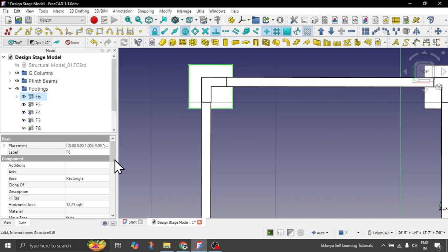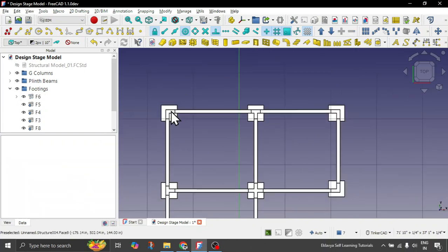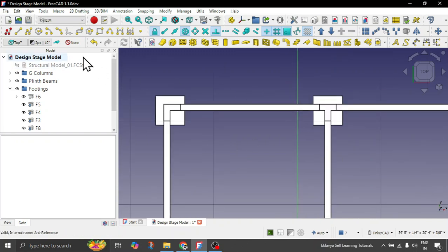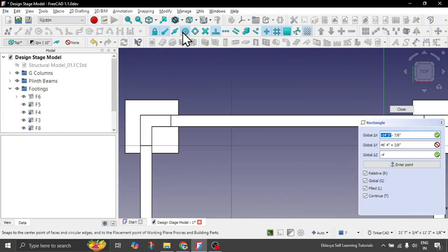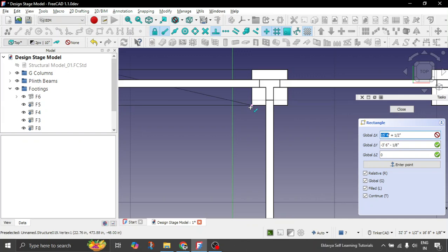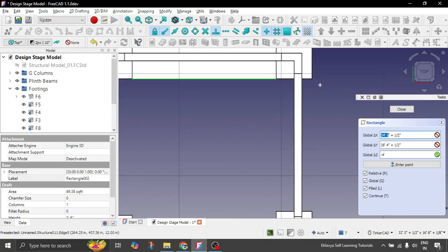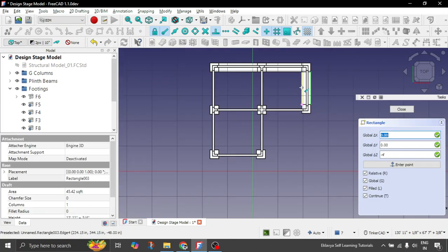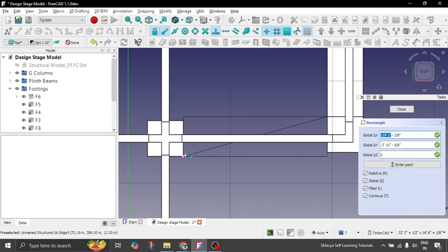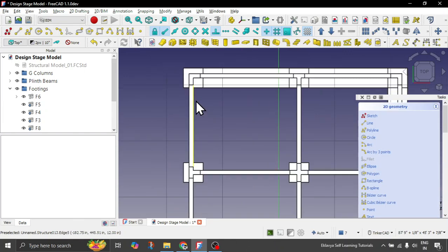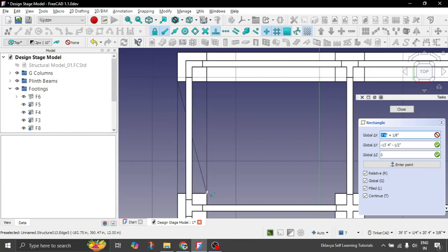So these footings were basically of height 5 inches. Yeah. So make sure you have top view totally aligned. Now we will basically draw the quick rectangles now. So choose a rectangle. Let's make the end snapping point. Click this option and now this one. Done. Click on this one and then this. Done. Right? This one will be very quicker. Done. And this one till okay, here we will have a little bit of, okay, we'll adjust this, no problem. This is aligned.